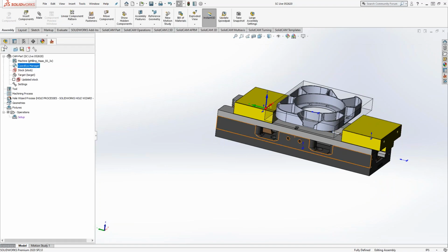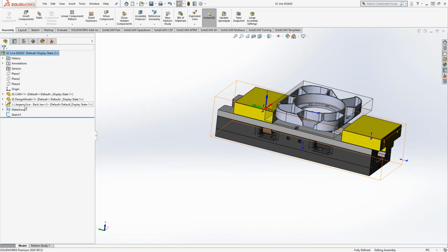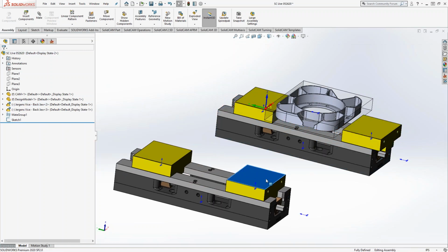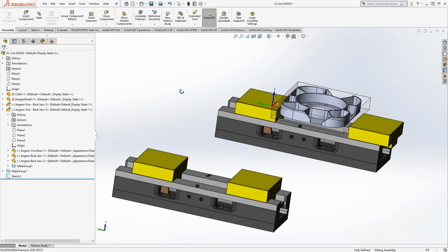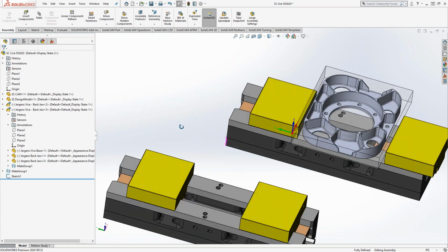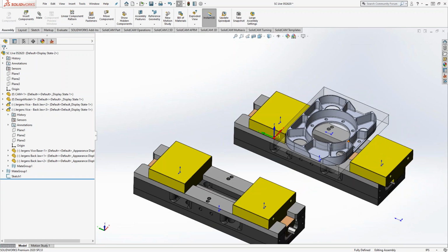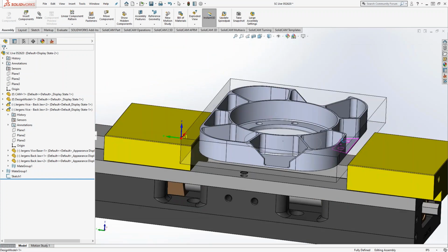So I believe we covered this previously, but the way we would do that is, since I set this up as a separate assembly, I'll hold the control key, grab that, and bring it over, and now I have a second copy that should have its own looseness there. It's floating. I can assign this for my second side. So if we want to basically hold it, maybe in this case, we have to hold it a little differently, I guess, because once we machine this, we're not going to have that same space there.